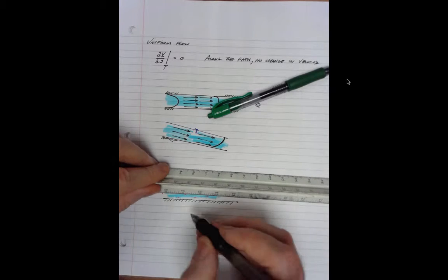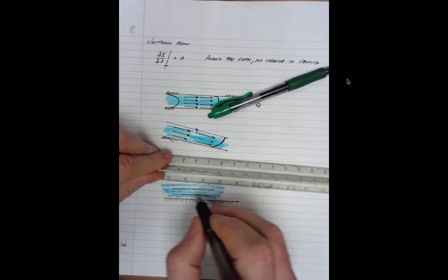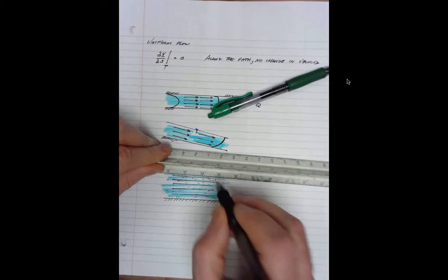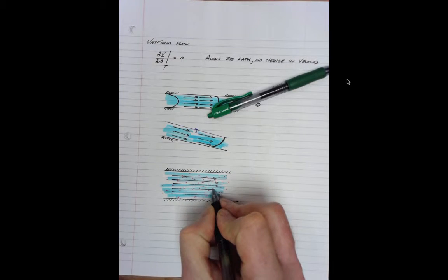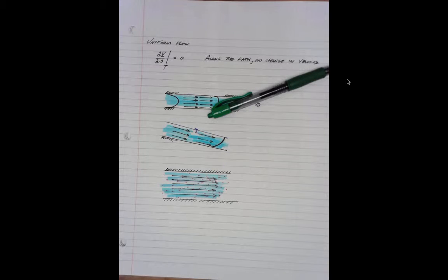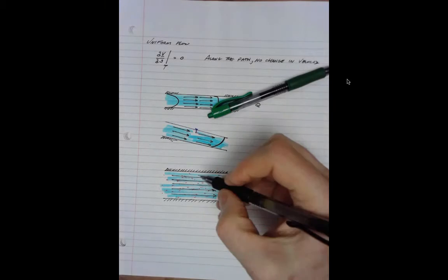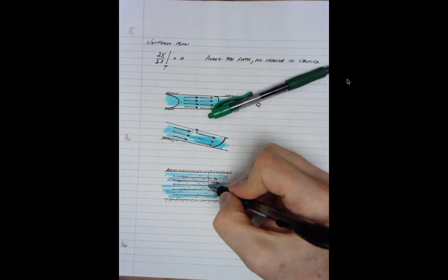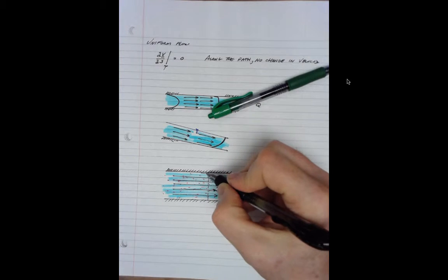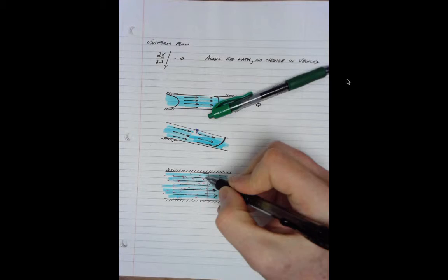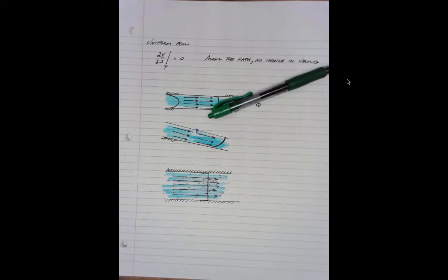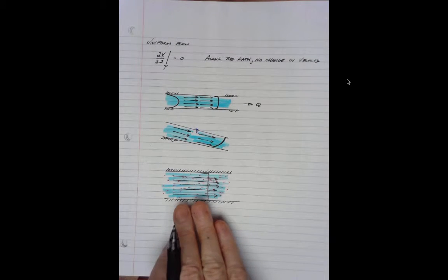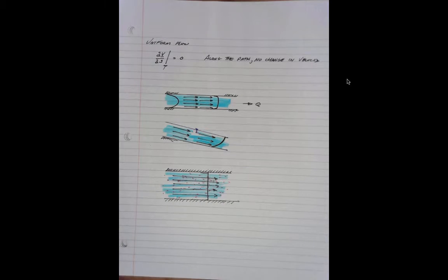And again, under many conditions, we get nice parallel flow. And usually in aquifers, the velocity profile looks something like that. It's almost a straight line. That's because the component of velocity is pretty small in a porous media flow. So we take advantage of that and pretty much assume this profile.